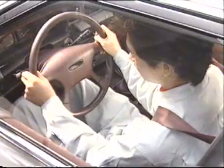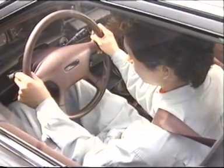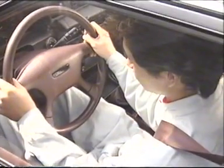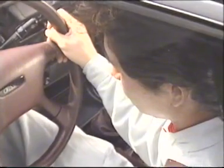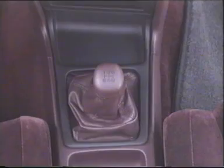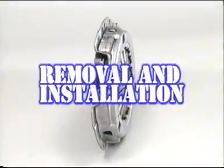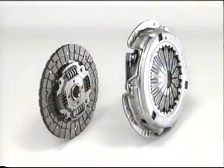And repeat, both slowly and quickly, to check the presence of unusual sounds from the clutch. If unusual sounds or noises are heard, check to see if they come from either the clutch or the transmission side. If trouble is found in the course of the on-vehicle inspection, it is necessary to remove the clutch cover and the clutch disc for further inspection or treatment.